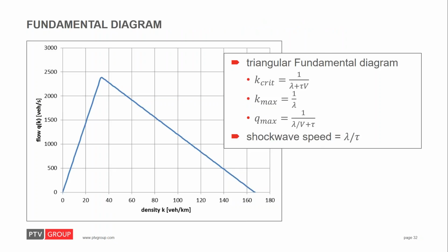So now we move on to the question of how to calibrate the model. First of all, it is important again to note that any error in modeling has more drastic effects in dynamic assignments than in static ones. For example, this can result in grid locks. So therefore, we would strongly recommend to first model the network correctly, and then you can start calibrating the model.